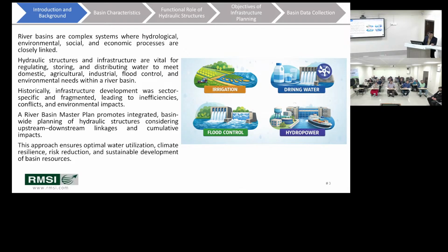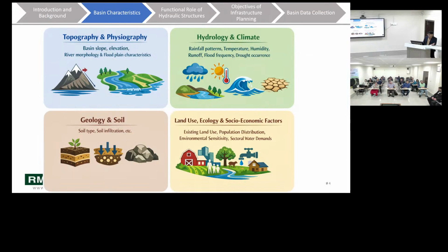Then you should consider what the climate stress will be after 50 years, 100 years. All those parameters you should consider while designing this structure. Topography you need to study, physiography, soil condition, land use pattern, social and resettlement issues.